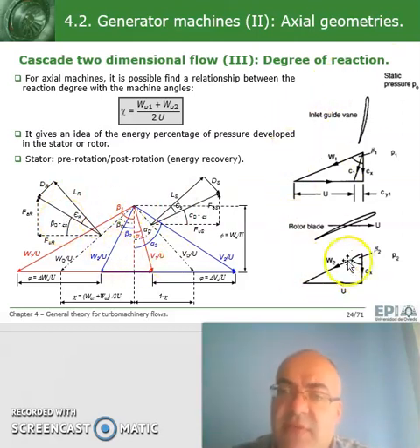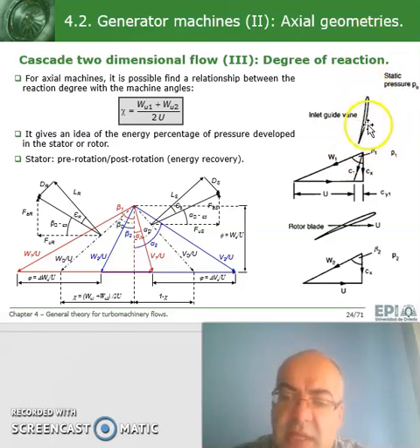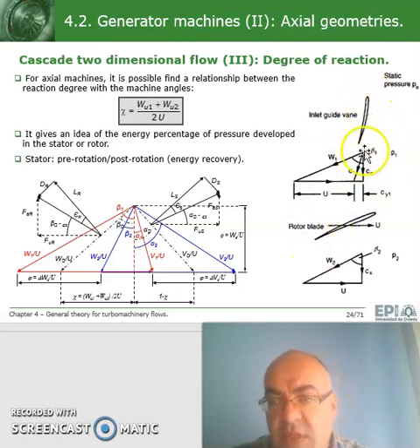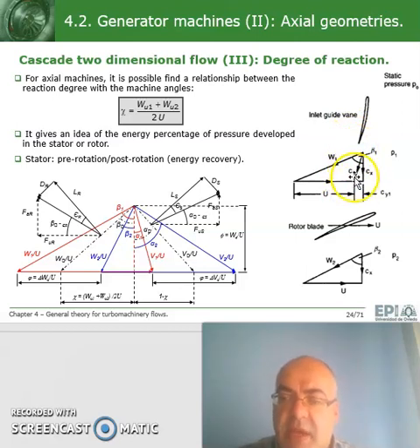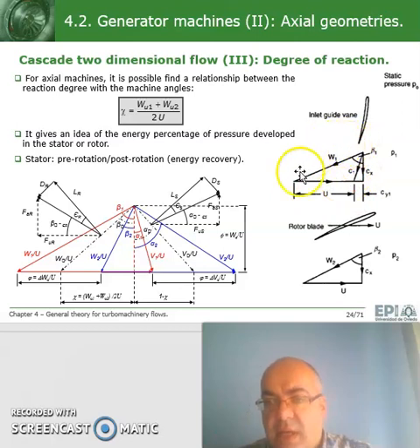And here on the right we have another sketch of another cascade analysis with other blades. In this case we have a stator at the inlet, and then rotor, so stator and rotor configuration, flow going down in the vertical direction, changed to V1. Here V1 is named as C1. We have this change in nomenclature due to the book where we took this drawing from. But as you see, W1 plus U1 is equal to V1 at the inlet, and the same happens at the outlet. Outlet triangle being here, W2 plus U2 equal to V2.